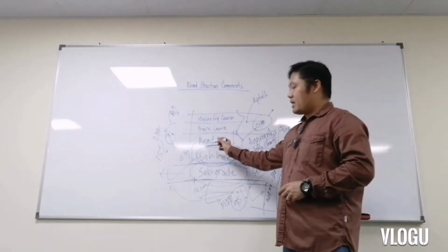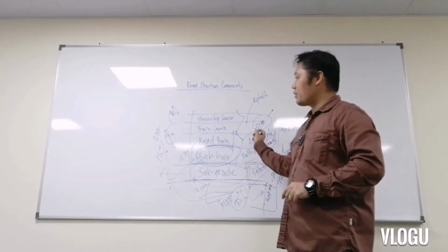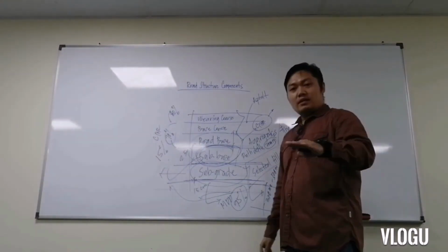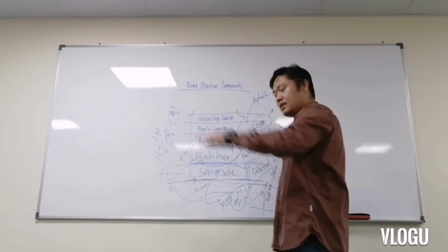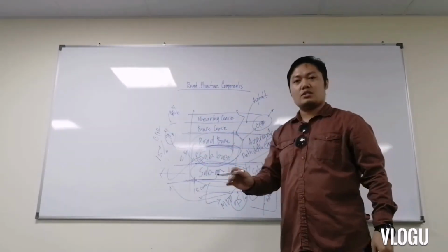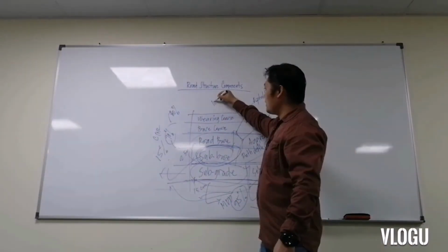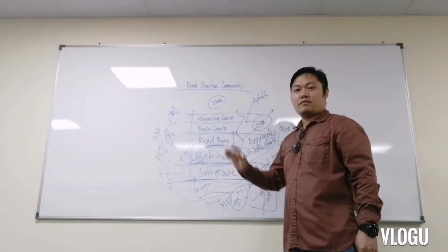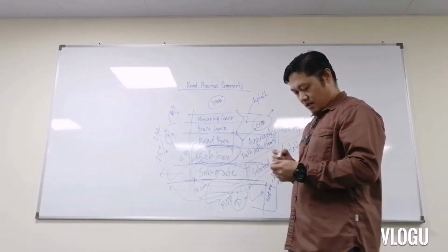And then at the same time, we have to conduct also the surface evenness testing before we proceed to asphalt works. So for surface evenness, what is the maximum depression, or the evenness of the top surface of the roads? We are going to achieve at least a maximum depression of only 10 mm. The maximum depression for the surface evenness on the road base and subbase is just 10 mm.